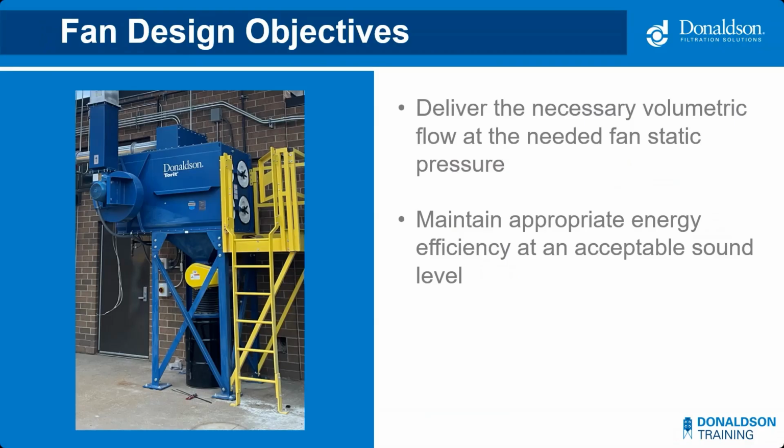First, a fan must deliver the necessary volumetric flow at the needed static pressure to drive operation of the system. Since collectors can operate with clean or dirty filters, the required airflow must be maintained over a range of static pressures. Secondly, the fan you select should be able to deliver the desired static and airflow with an appropriate energy efficiency at an acceptable sound level. Those are the challenges.